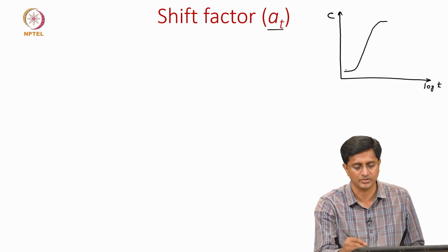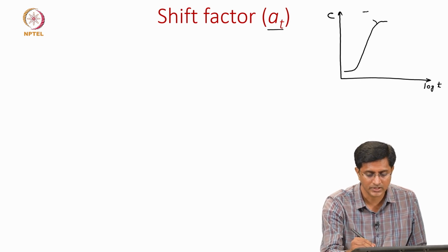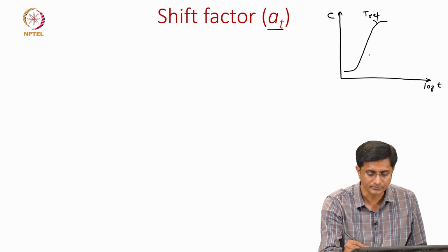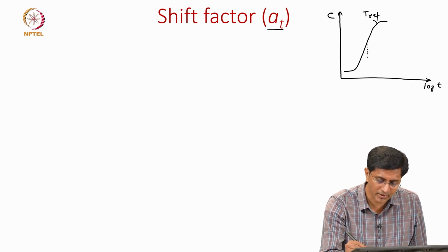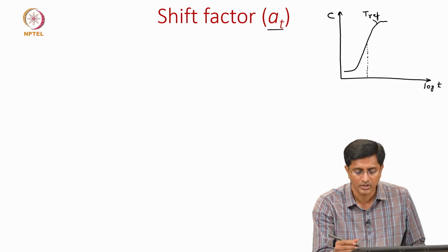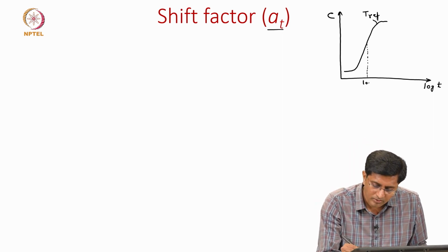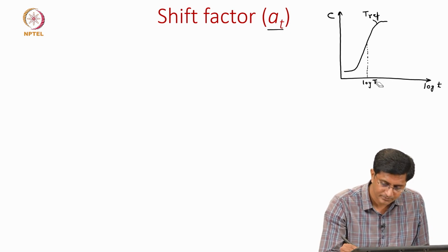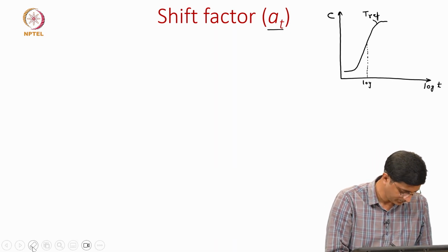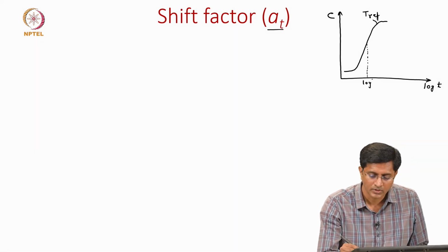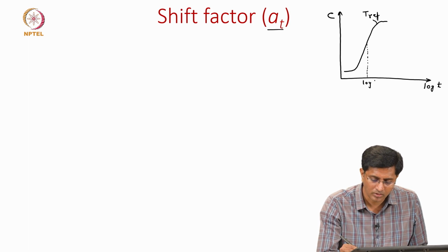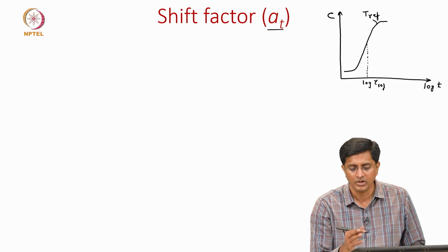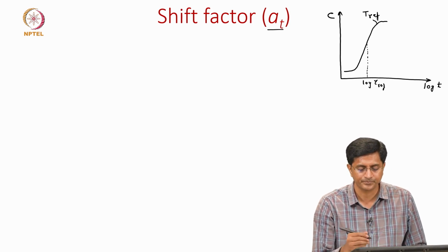at a reference temperature. So, let us say this is a time t ref, and this corresponds to a relaxation time or the retardation time, log tau ref, where tau ref is the relaxation time corresponding to the reference temperature.